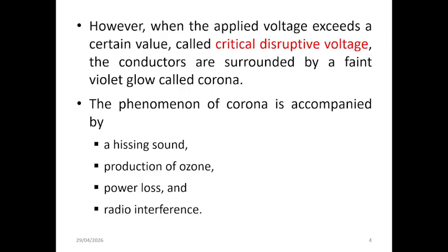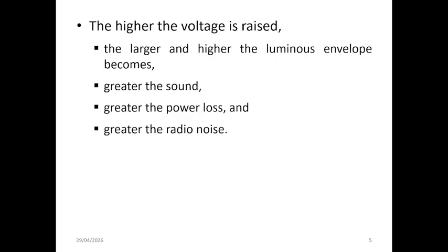Corona produces a hissing sound due to the rapid movement of charged particles in the air. It also leads to the formation of ozone because of chemical reactions in the ionized air. In addition, corona causes power losses in the transmission line, which reduces system efficiency, and it creates radio interference that can affect nearby communication systems.